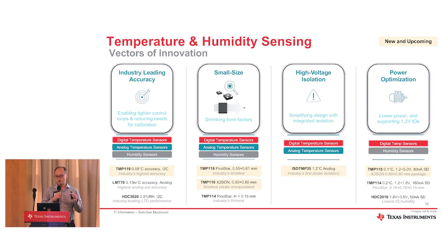And we also do low power consumption. Because in the past, maybe you do 4 channels of temperature sensing. Now you want to do like 30 or 40 channels of ADC for temperature sensing. Then that will cost you a lot of power, right? So we make it low power so you can put more temperature sensors across your entire PCBA.